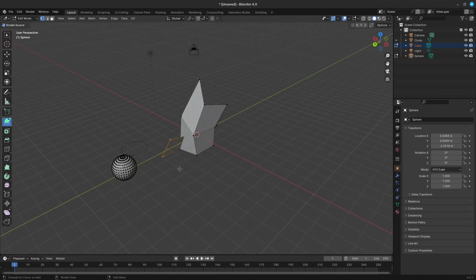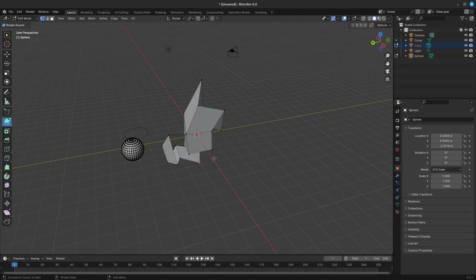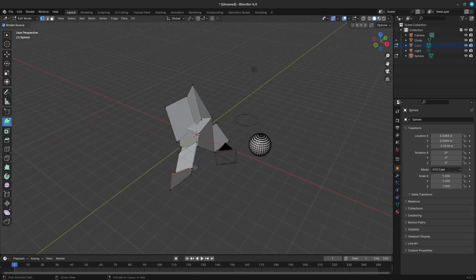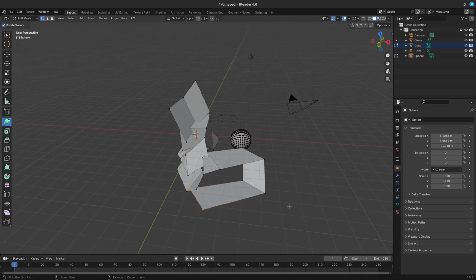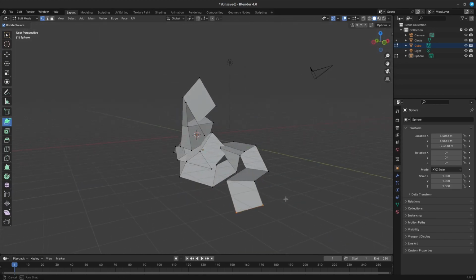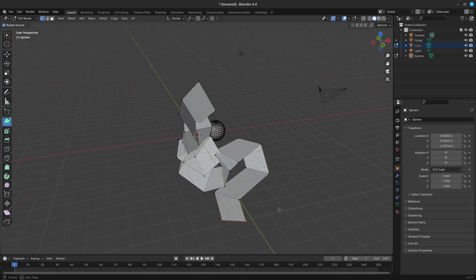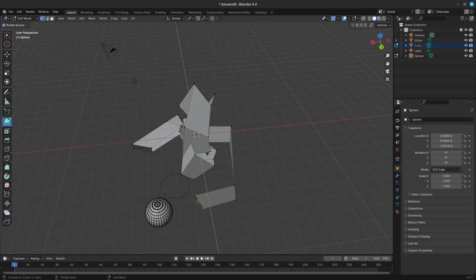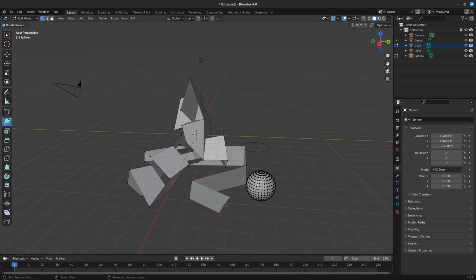For Control plus the right mouse button, Blender will automatically rotate the last selected edge, the source, for the subsequent operations if you have at least one face created, dividing the angles created between the newly created edge and the last two edges, creating a smooth angle between them. Blender will calculate this angle using the last positive and negative position of the last X and Y coordinates and the last connected unselected edge. If this angle exceeds a negative limit, following a quadrant rule, between the recently created edge and the last two, Blender will wrap the faces.